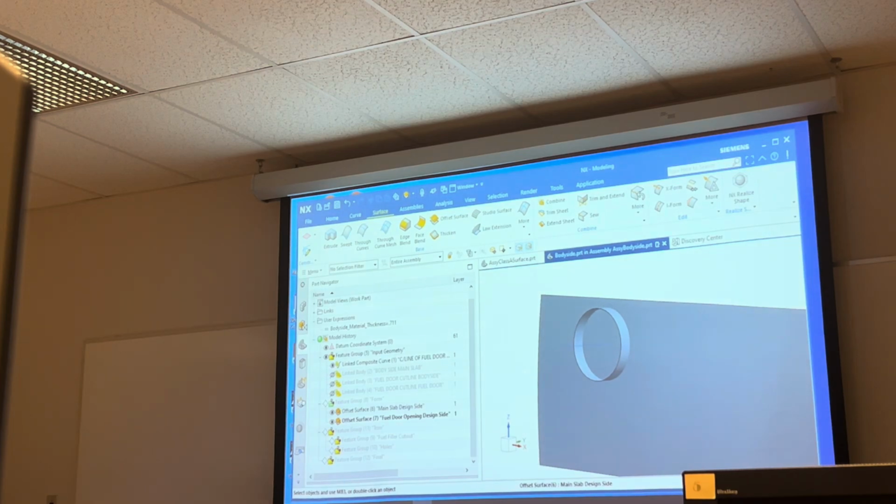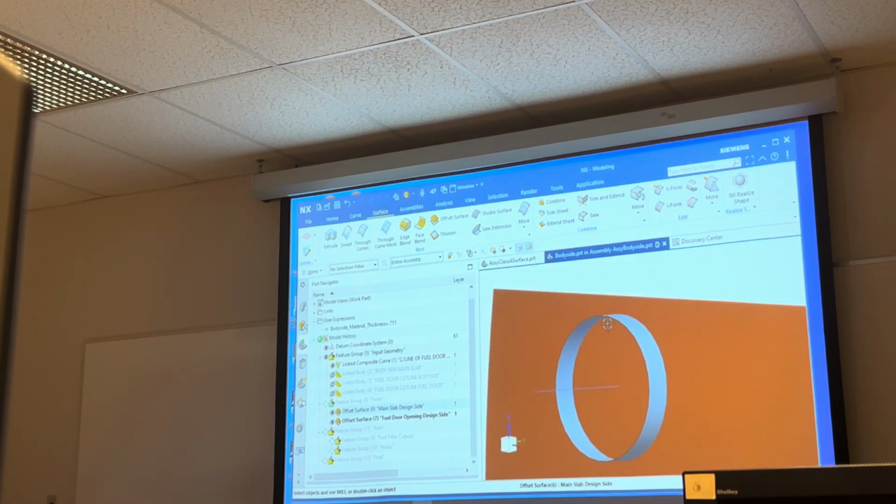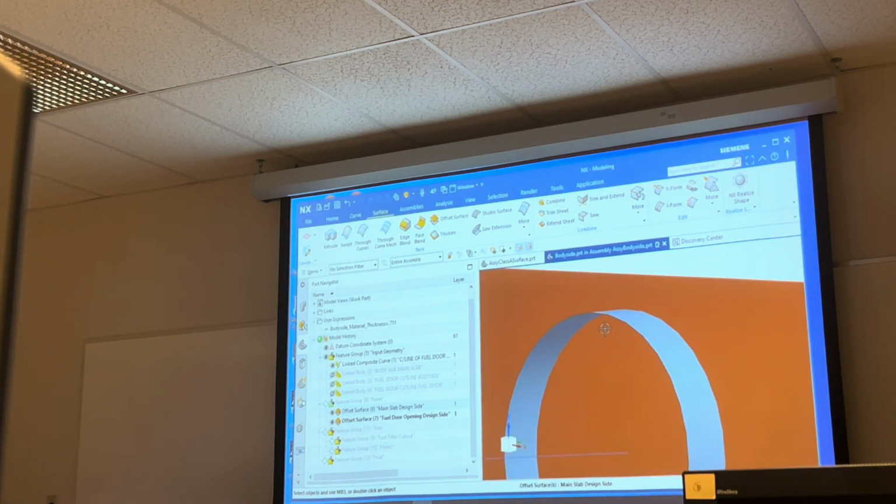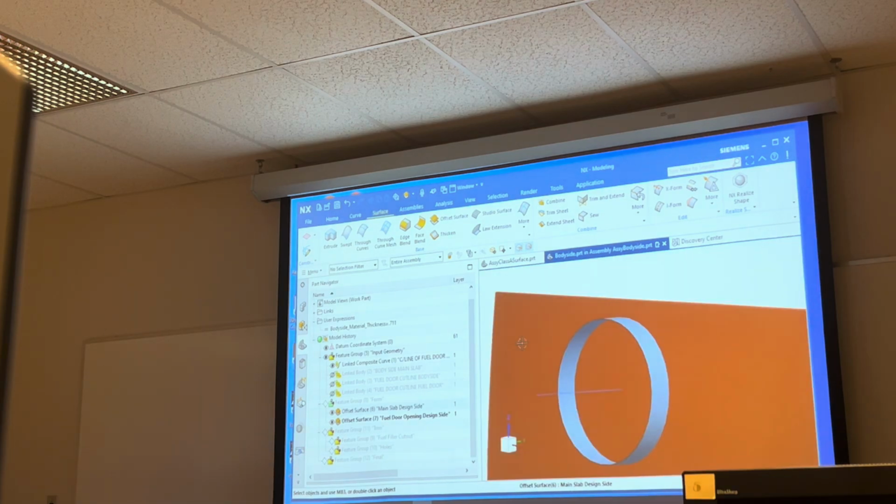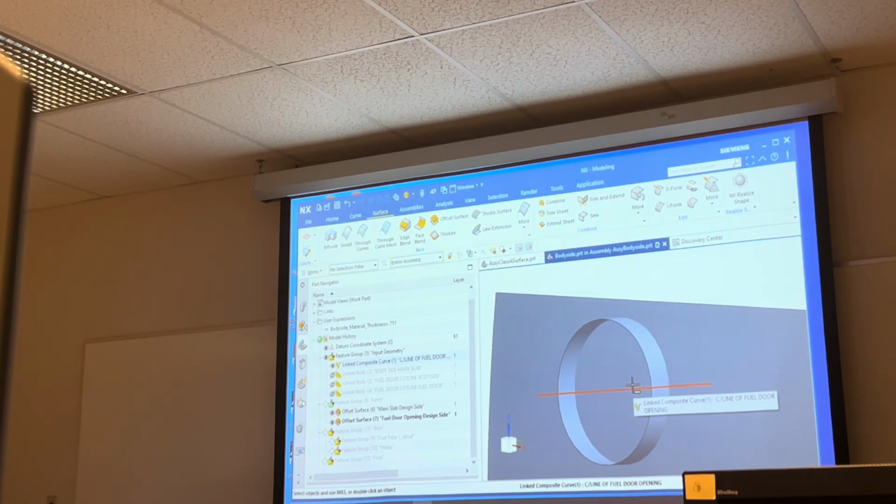They worked with their knowledge of sheet metal, which is really important. There's bend radiuses for certain types of sheet metal. So they know that for this type of metal, the bend radius, the fillet radius, where it comes across and then it goes down into the pocket, that should be no more or no less than 3 times the material thickness. All right. So that's why they're doing this, because they're using these rules. Because if you try to bend it smaller than that, it'll wrinkle or it'll tear or something. So they're doing this little method here.